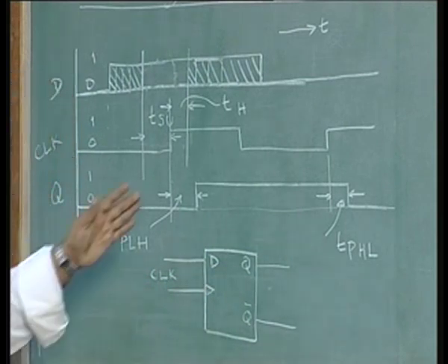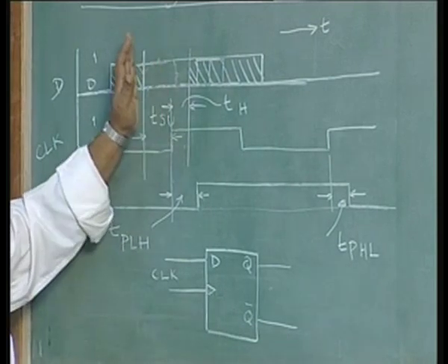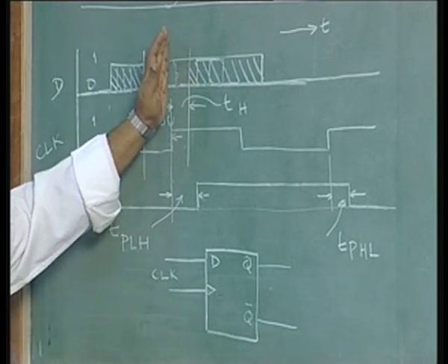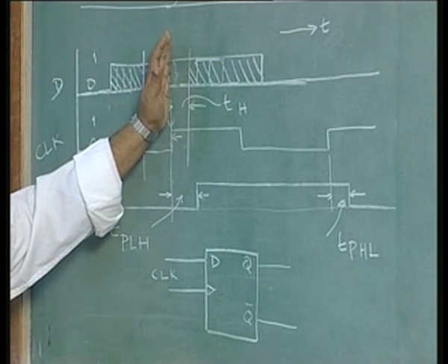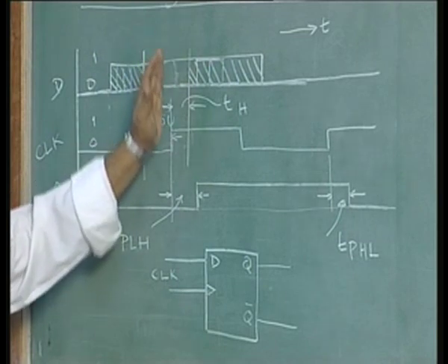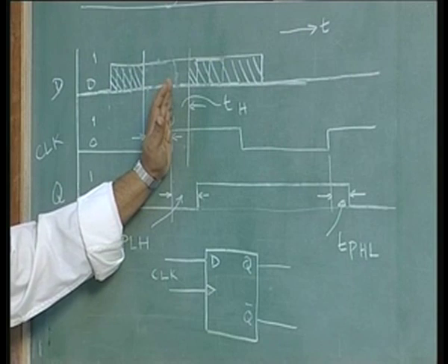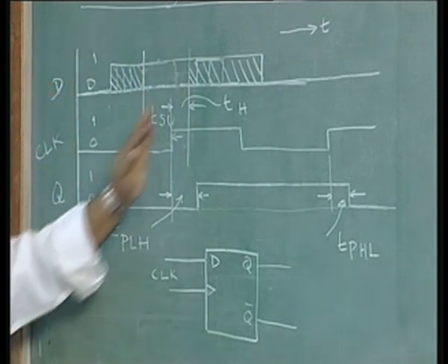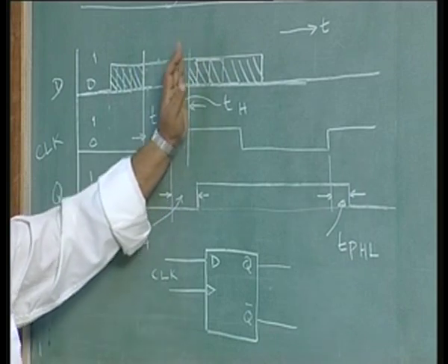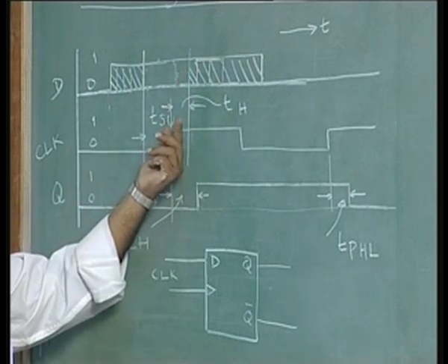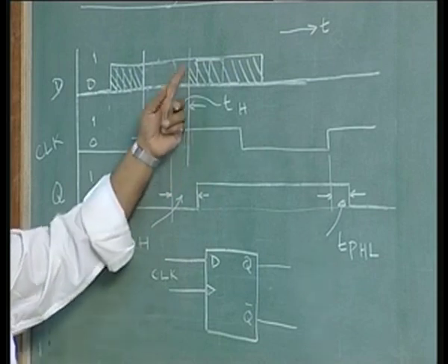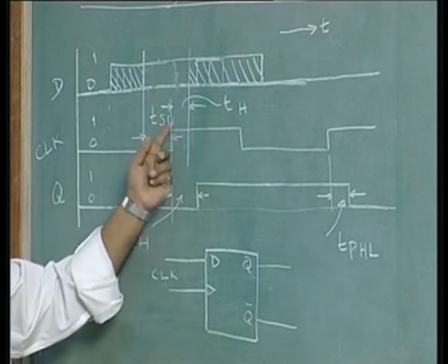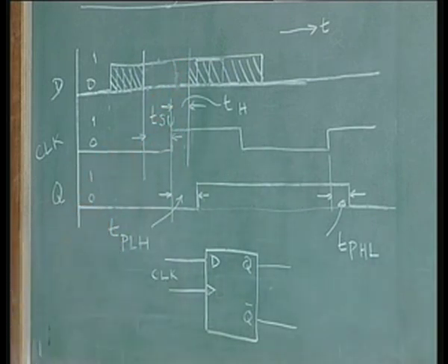And then we are talking about 2 other terms. One is called the setup time, the period or the interval or the duration before the clock transition at which the input should be stable, and the hold time is the period for which the input should be stable after the clock transition has occurred.